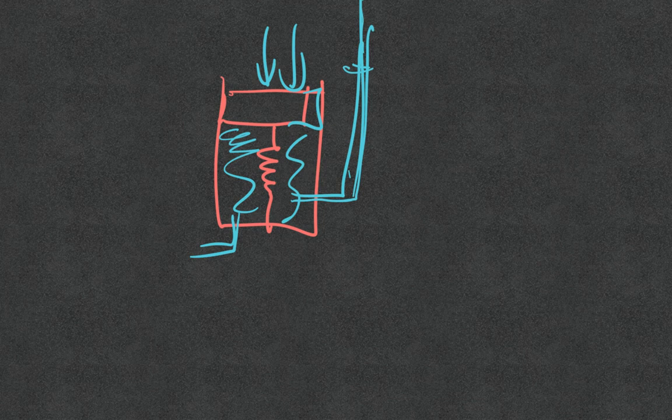Now in the undrained case, let's say I shut down the outlet. I don't allow water to escape. Then when I'm pushing it, the only thing that can happen is that the incompressibility of the fluid will play a major role in resisting the piston that's pushing it down, right? So the excess pore pressure loses the ability to dissipate. Does that make sense? Because I don't allow any drainage.